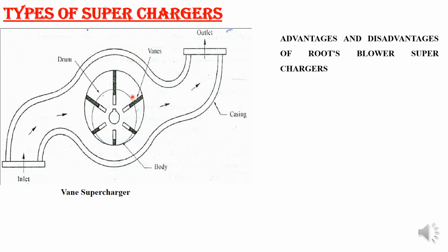So this consists of a rotor rotating in a large cylinder, which has six slots, and the vanes remain in contact with the casing at least at one point at a time. The axis is mounted eccentrically. You have just studied this part, and I am going to repeat it. Already you have studied this vane type of pump. So in the eccentric type, the center is eccentric.